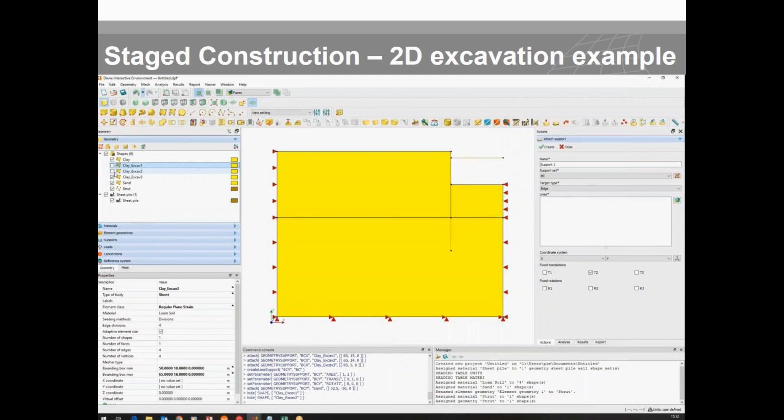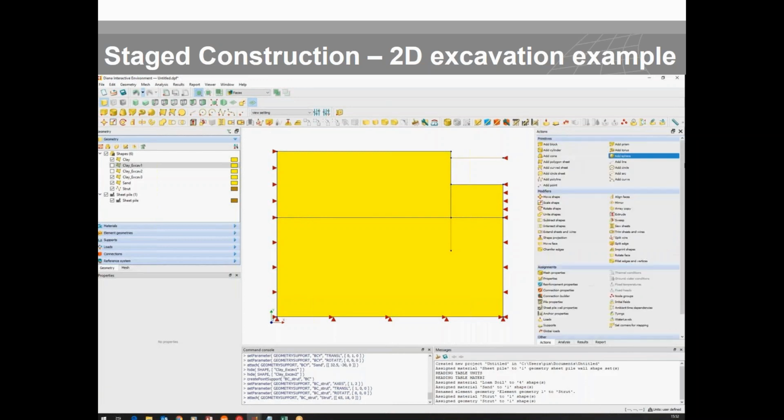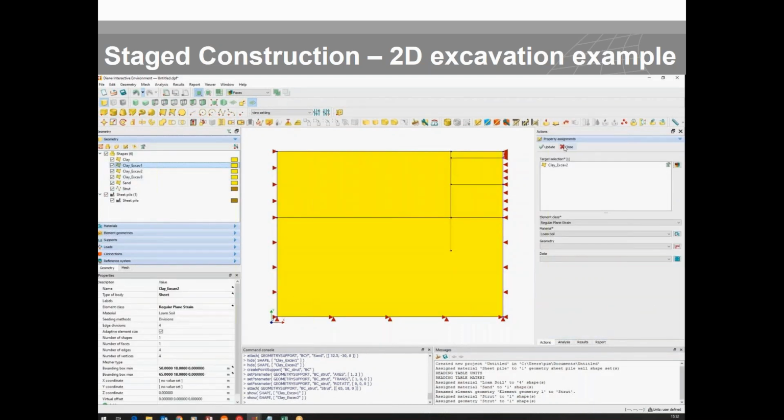And for the strut, we're going to repeat the same, but in the symmetry direction, we only constrain it in the X direction. So we call a new BC strut, again under the same boundary conditions. This time we change the selection to the vertex. We select that, and in the X direction, create. Beautiful. So if I expand my support, you can see under the BC, I have all those supports assigned.